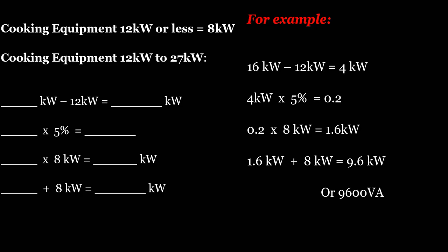And if you have a kitchen that has a full standing range, then there's your calculation. If you have multiple appliances, let's say you've got a cooktop and then you also have a double oven over here. If they're all in the same kitchen, you can add the kW load of all of those together and then calculate them just like I've shown you as a single appliance. Now let's say you've got a house that has maybe a kitchen in the basement, in the man cave, or you got a mother-in-law suite, bless your heart. But anyway, if you got a second kitchen, then you would calculate those differently. But if they're all in the same room, there you go.